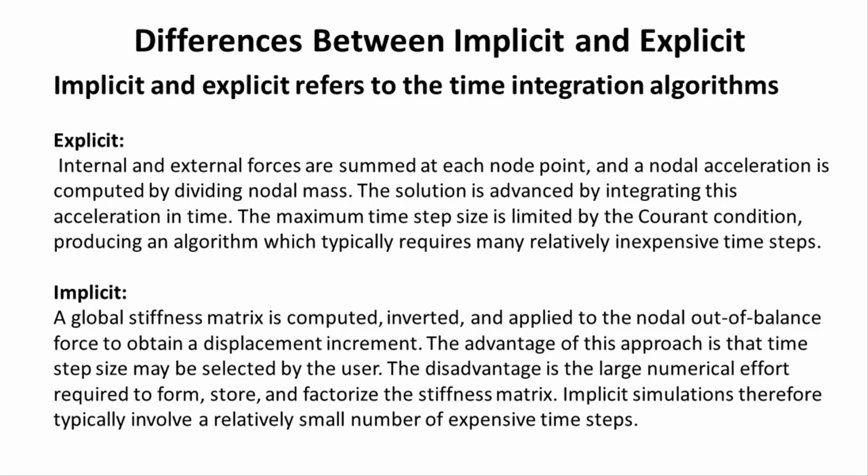The implicit and explicit are defined by their time integration algorithms. In the explicit time integration algorithm, internal and external forces are summed at each node point, and a nodal acceleration is computed by dividing by nodal mass. The solution is advanced by integrating this acceleration in time. The maximum time step size is limited by the Courant condition, producing an algorithm which typically requires many relatively inexpensive